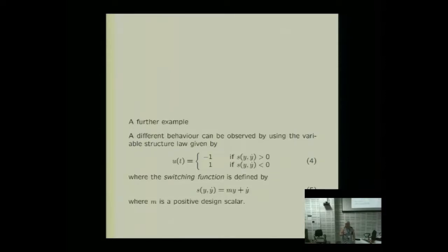And this paradigm that says the control is not defining the performance is very different to the paradigm of a typical controller. Almost any other control design, people design the controller and think, well, I tune this parameter in the controller, I change the controller, and it changes the performance. In a sliding mode controller, we will see that for a given performance, you can have an infinite number of controllers that give you that same performance. So there is not a 1-1 mapping between controller and performance. And that's the first very, very important thing to take away from this.